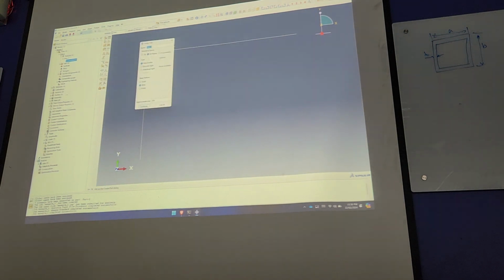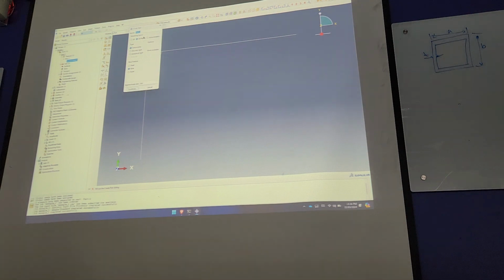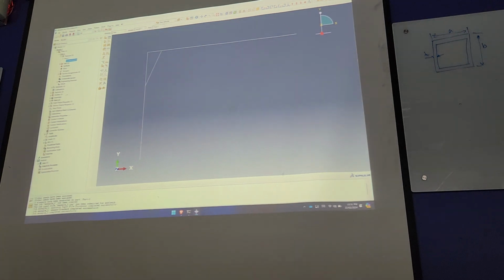When you create a part, you choose 3D, deformable, and wire or structural element, because we are interested in those lines. We are not interested in what is enclosed. When we are dealing with continuum elements, we would choose shell, which means whatever we enclose with those lines is the actual material that we are capturing. In this case, I picked wire and got a geometry.